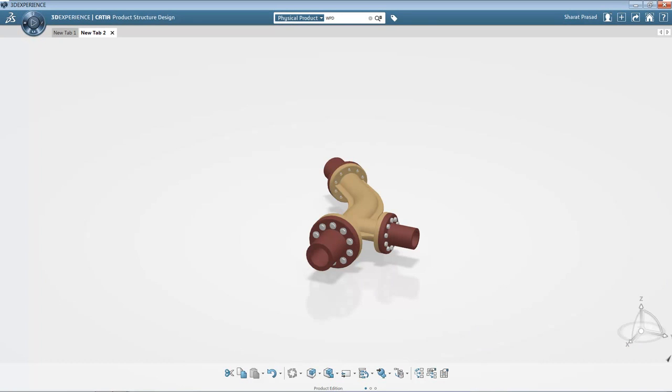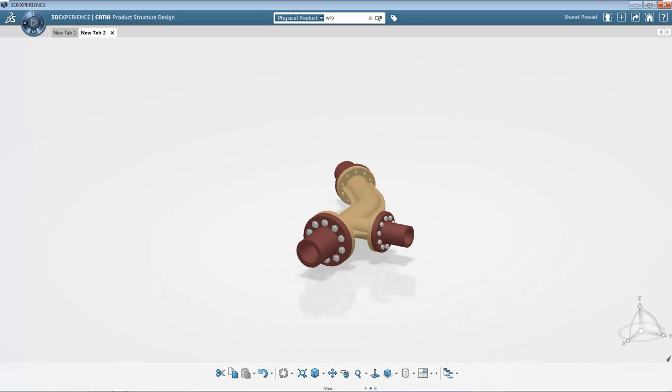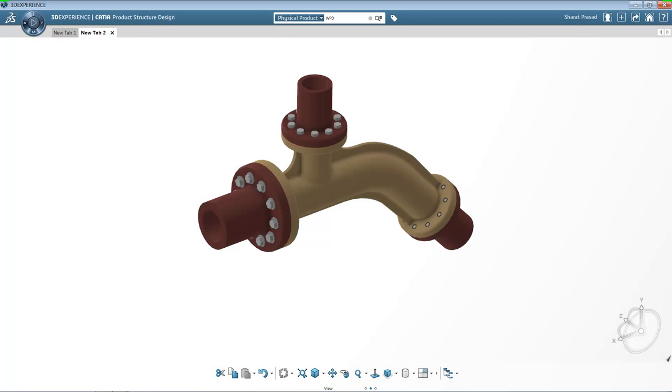As you can see, the pipe assembly has two inlets and one outlet. I'm going to set up a thermal mixing simulation. The fluid is going to flow in from one side, and the fluid is also going to flow in from the top inlet, and the fluid that enters from the top inlet is going to be somewhat hotter than the fluid that is entering from the left inlet.